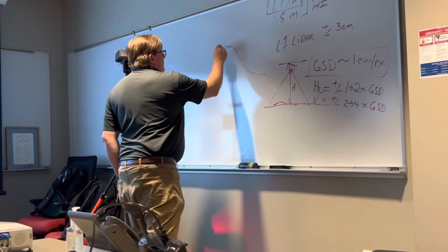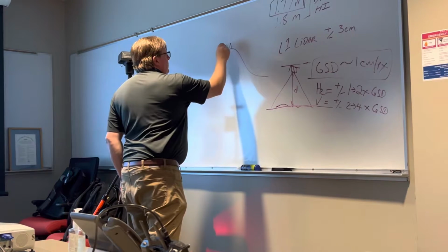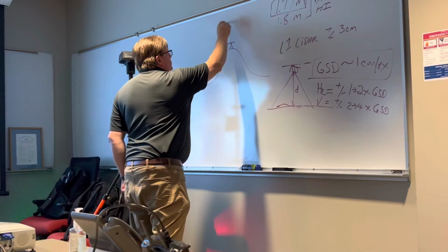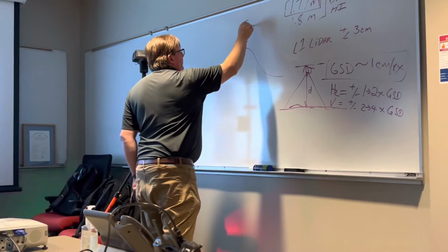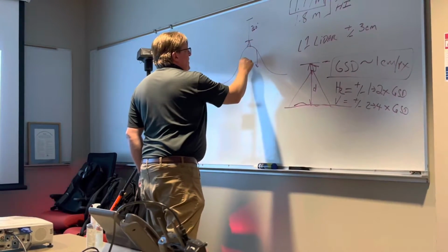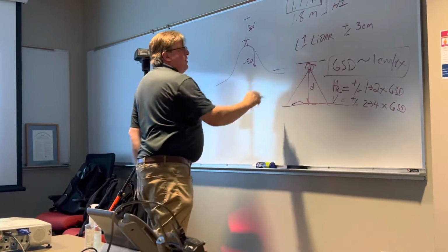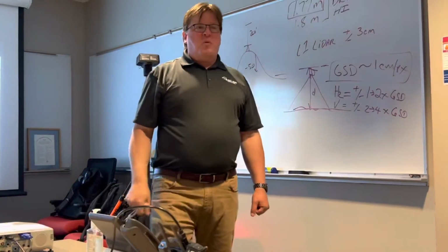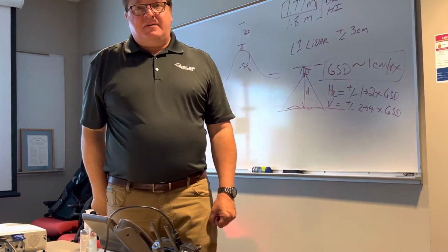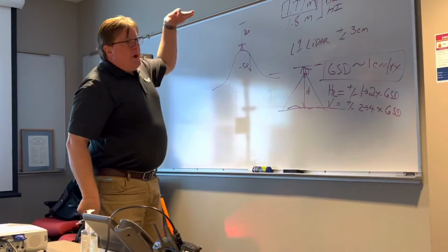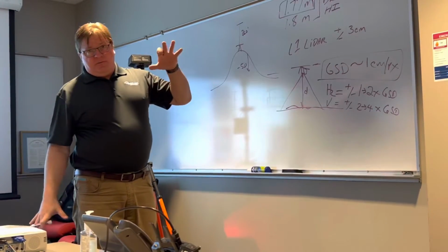Now, that does change, because of the way the drone works. This is a profile view. If I take off from here with my drone and fly up at 260 feet, and the ground drops away 50 feet over here, my ground sampling distance is going to be more like 1.34 centimeters instead of 0.99. So the terrain is going to average out.